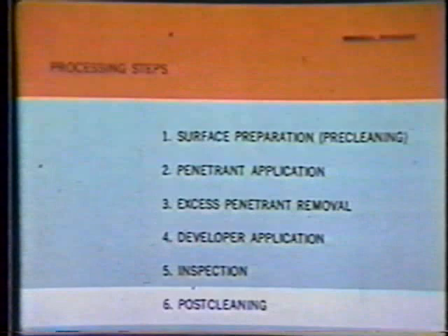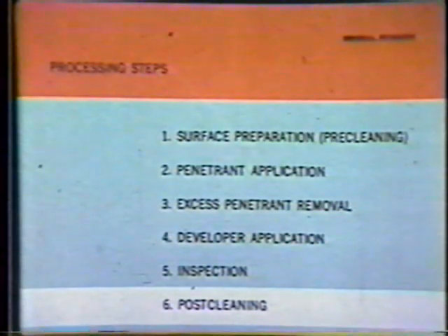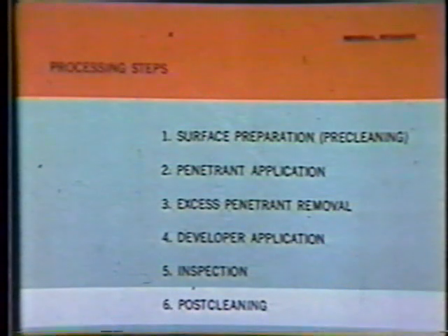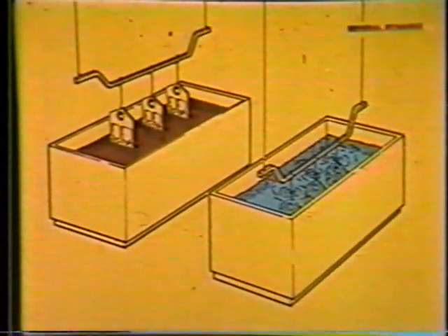Our final example is this machined steel fitting. The crack indications are typical of indications occurring at points of high stress. Because penetrant and developer residue attracts moisture and may cause corrosion or may interfere with subsequent processing or usage, the final step in liquid penetrant testing should be a thorough post-cleaning. Methods employed are the same as those recommended for pre-cleaning. Detergent cleaners produce the best results in removing water-based materials. Vapor degreasers are best in removing oil-based materials.